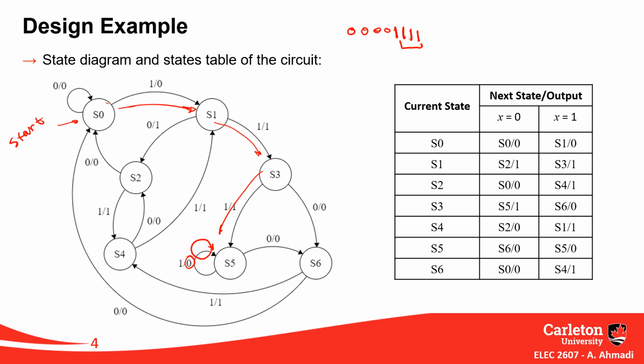If you get 0, you move to state 6, which gives you this input, right? And this will be the new number, which is 14 and is not prime again. Your output will be 0 and your state will change, and so on and so forth. As we discussed in class, as you have seen in other examples, this is the state diagram of the circuit. The next step was, or is now in this presentation, to convert this state diagram to a table.